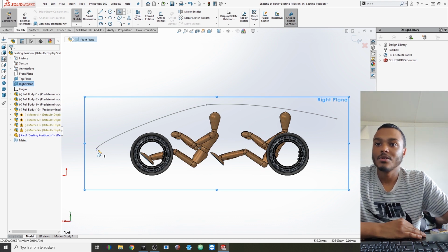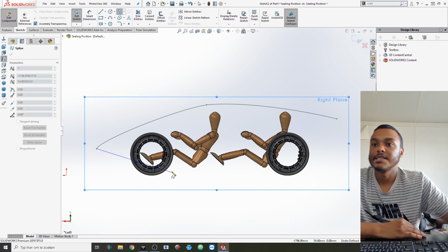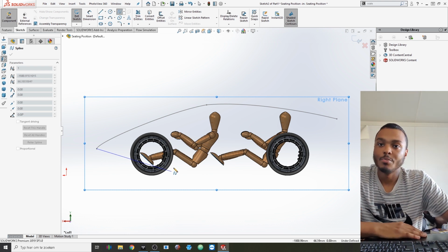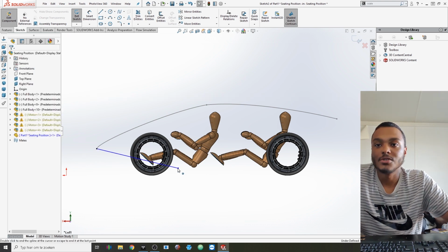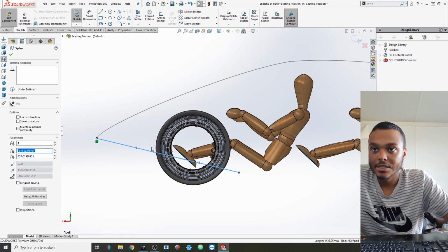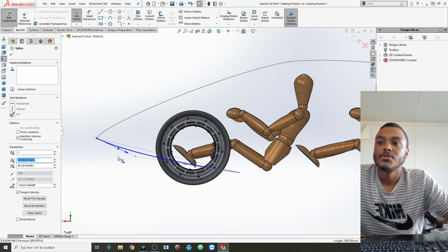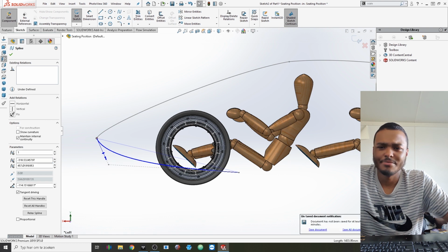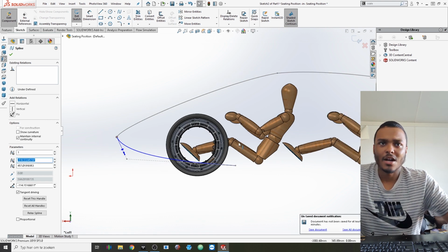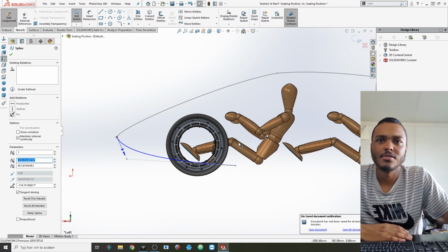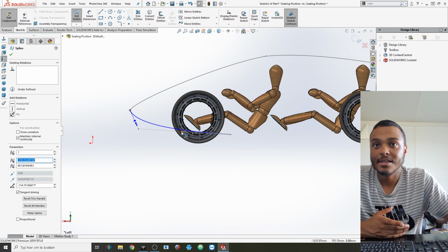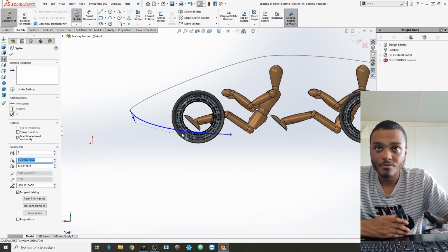What the spline tool gives you the freedom to do is just drag it and drop it, and also use multiple points in there to get it configured how you want. So for now, I'm going to make the underside and the under tray of the car as well. I want this car to have a very aerodynamic profile, but also to make it look a little bit shark-like, I guess. So I want that whole shape to be very purposeful, and to do everything that it needs to. On the spline tool, you get these handlebars that you can drag and cross along and get the desired curvature.